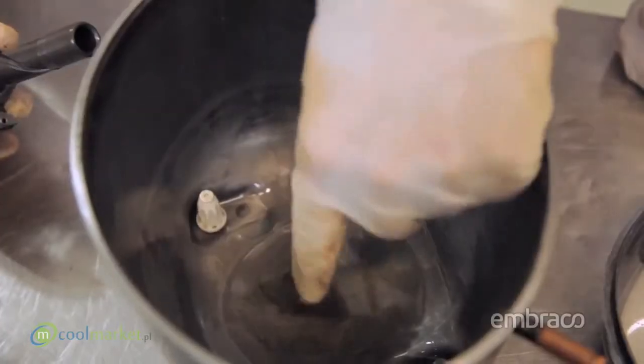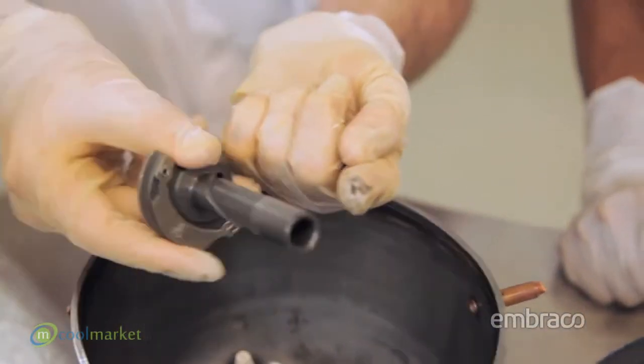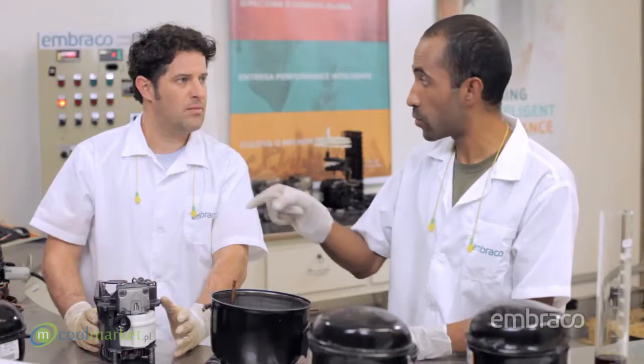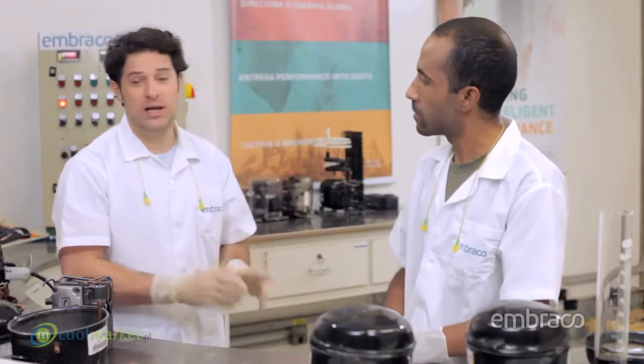I understand. If the oil circulating in the system doesn't return to the compressor, problems will occur. So this means that good sizing of the tubing and cooling system is critical for the oil to return to the compressor. And are there any problems involving excesses? Good question, Mark. There's one related whenever there is an excess gas charge, causing the rupture of the cylinder cover gasket or damage to the valve plate.